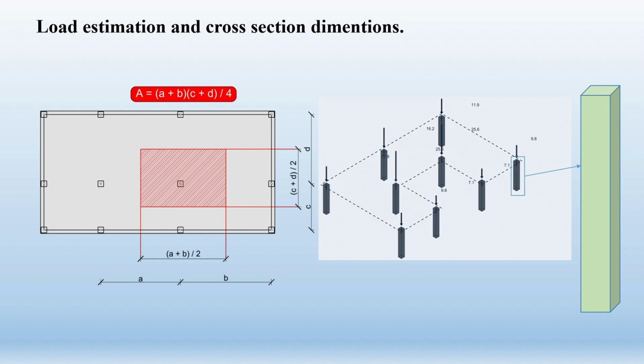Since the yield strength of the material is known, it is easy to determine the minimum area required to support the concentrated force acting on the column. It is important to note that the effects of the horizontal load generated mainly by the wind or earthquake and the second order effect should also be considered before giving out the final cross-sectional area of the column.